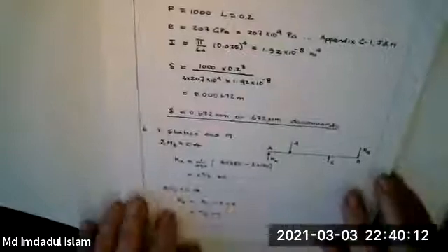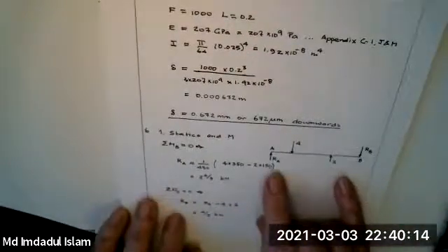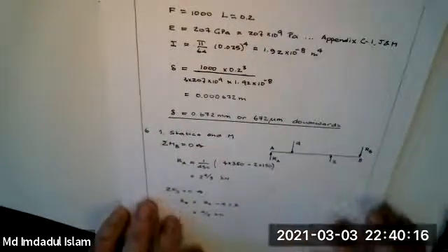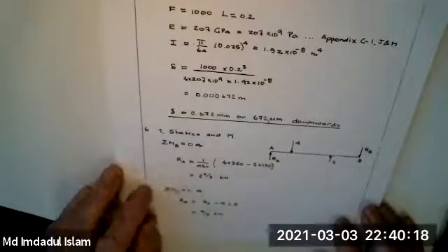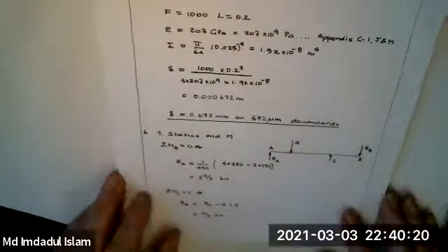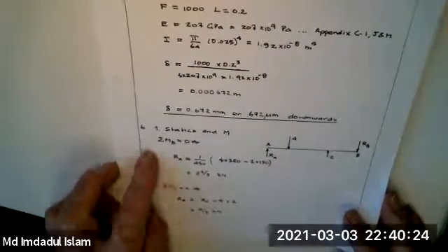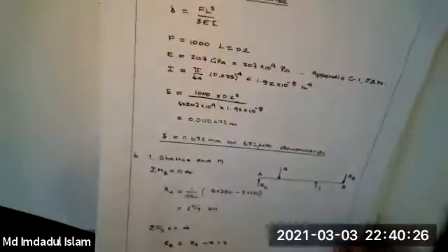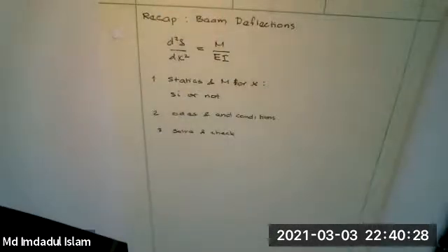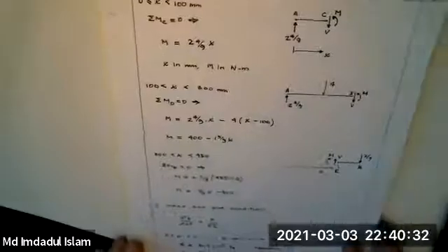So here's the statics, here's the given forces, here's the end forces, and you can solve. You have 2 equations in effect because there are no forces laterally, okay? And so I took moments and summed forces, and you can get reactions. And then once you've got the reactions, you can go get the moments.